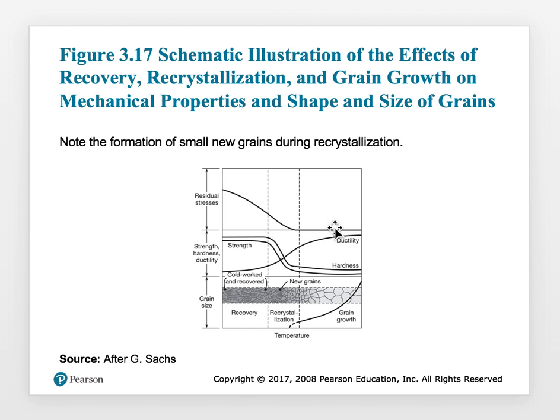So you recover some of that ductility, because increasing ductility actually increases the toughness of your material. And the other thing is that if you have done cold working, it makes it an anisotropic material. You do not want that to be the case if you can help it.